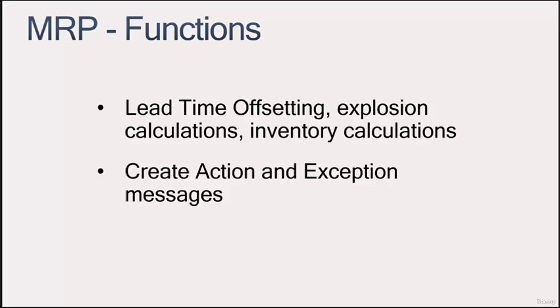In both cases, an external action needs to take place to address the messages in order for MRP to function properly. It should be noted that MRP is not programmed to issue or release orders. This is required by external action, such as a scheduler working in the company, who will physically release an order to begin work in the manufacturing shop, or issue an order to purchasing to go buy a part or material from a vendor. An example of an exception message could be to expedite or de-expedite a schedule for a subcomponent, change a quantity on an order, cancel an order, to name a few.